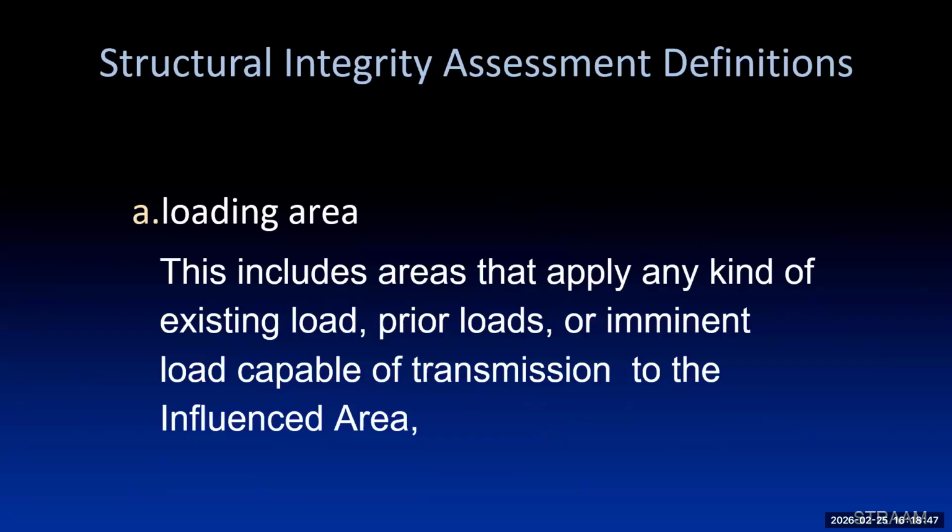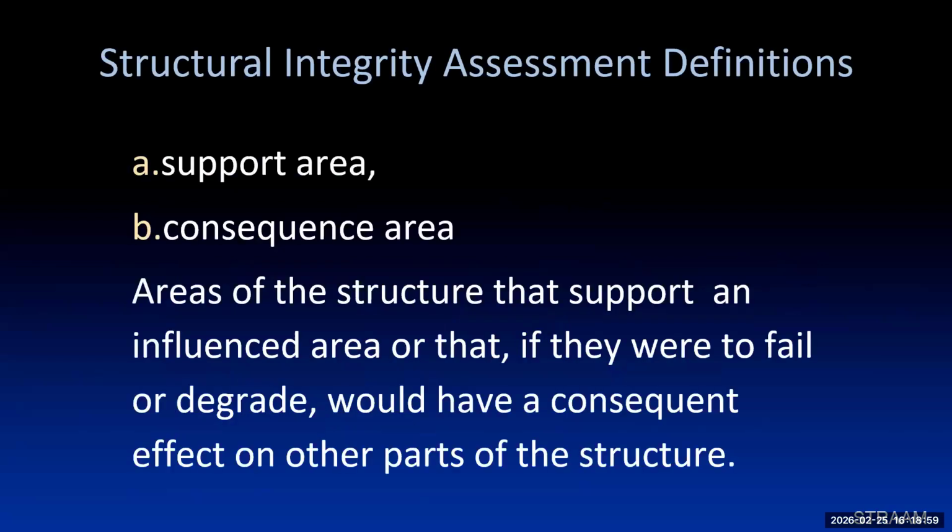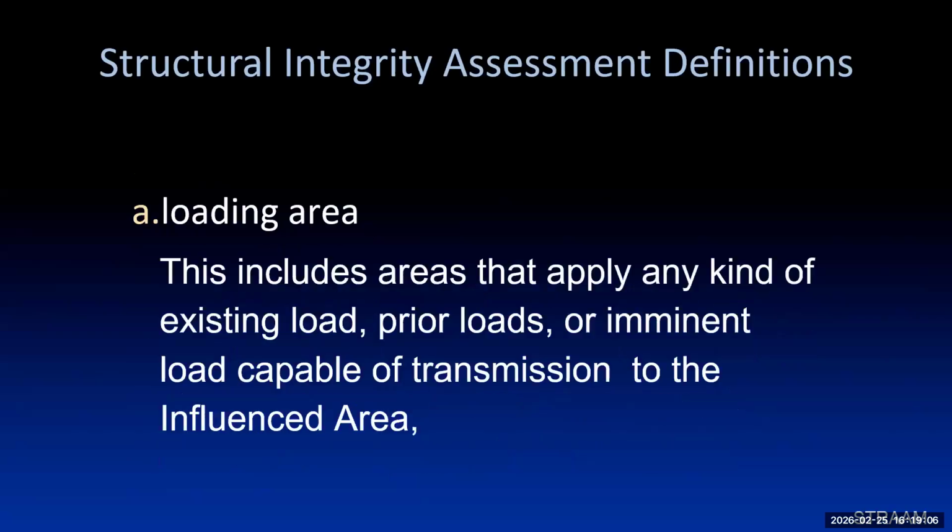The loading area includes areas that apply any kind of existing load, prior load, or imminent loads capable of transmission to the influenced area. Now, there is an important aspect to this, and that is that imminent loads include not only putting heavy things on floors, but also extreme winds occurring or an earthquake.